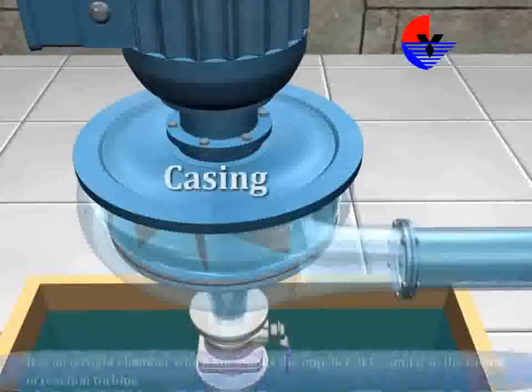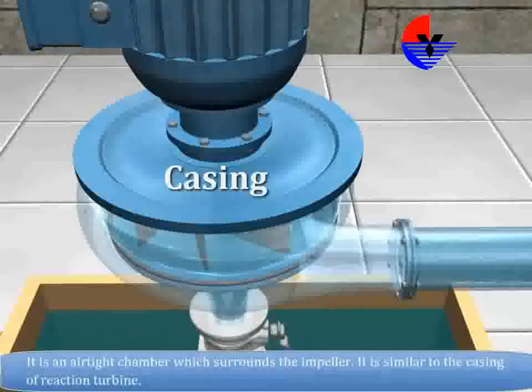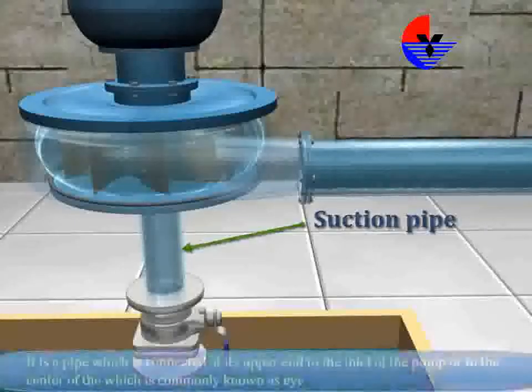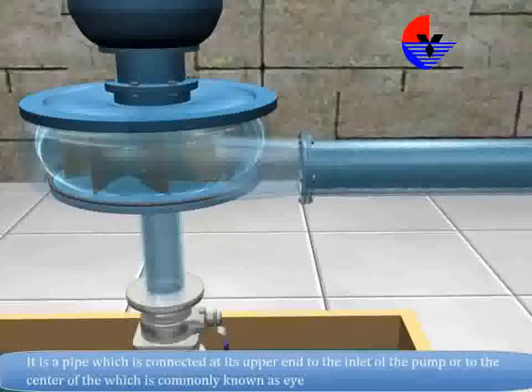Casing. It is an airtight chamber which surrounds the impeller. It is similar to the casing of a reaction turbine. Suction pipe. It is a pipe which is connected at its upper end to the inlet of the pump, or to the center of the impeller, which is commonly known as the eye.